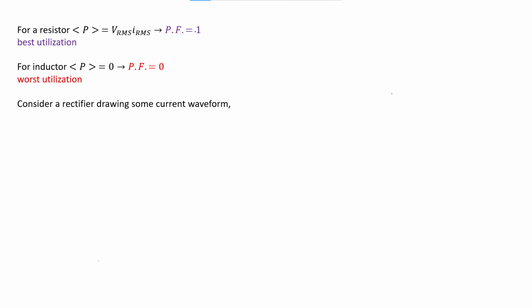But it's not the case, because when we use a motor, it has a winding, it has an inductor, flux leakage. Use a transformer, also there is some flux leakage, so we cannot have the ideal case. So in practice, if you can get a power factor of 85% or above, that's considered good.